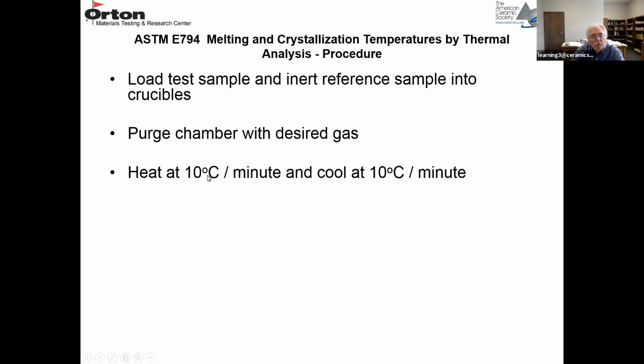Heat at 10 degrees C a minute and cool at the same rate. You have to heat relatively fast to capture the reactions. If you heat too slow, you'll get a very narrow or shallow peak. Heat at this rate, you'll usually get a good sharp peak.